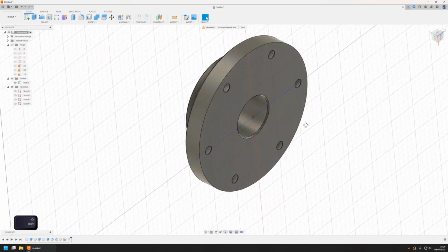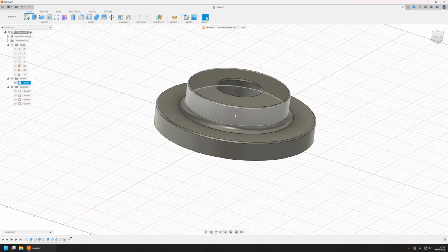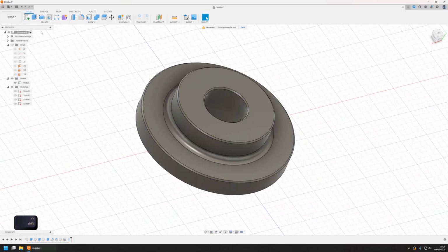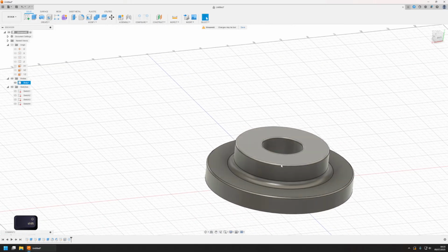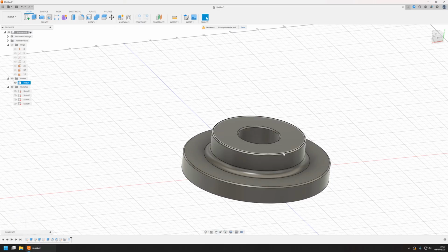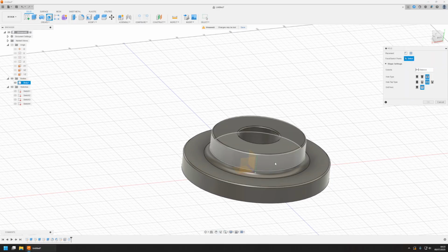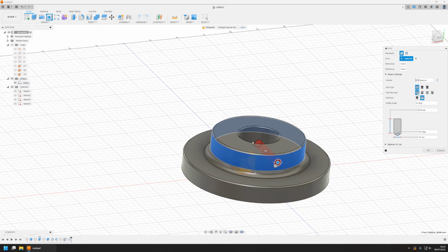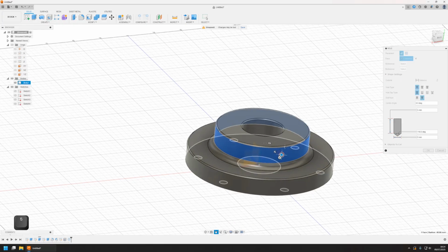Alright, that's very nice. Next, these holes on this surface here, which is going to be slightly more tricky, but as you will see, very simple. So the way we do these holes on this surface is we select the hole feature, we click on the surface that we want the hole in, we select our type of hole. It's going to be a simple hole, no tap, angle bottom, 180 degrees. It's going to be 5 millimeter diameter and 5 millimeter depth. Not 56, 5. Yeah, that's good.